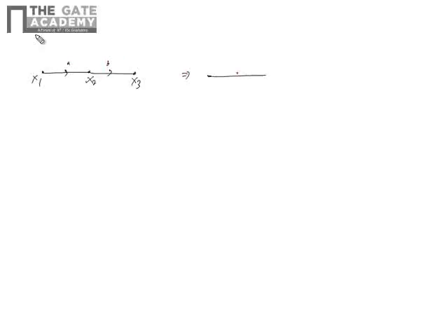So it can be written as a into b, x3, and this is x1. Another representation is this is a and feedback with minus b. This is x2, x1. So x2 equal to a by 1 plus ab. Why 1 plus ab? Because it's a negative feedback, right?